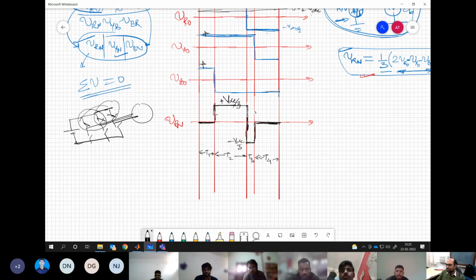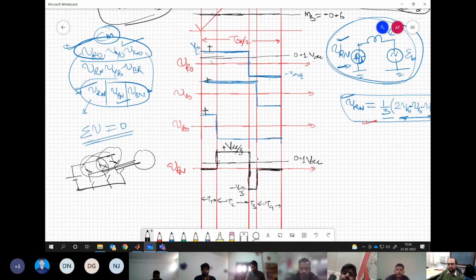They're the same thing, but in a different way. Same fundamental, yes, sir. In a different way means only the common mode is gone. Correct. But the average value will remain the same. It will remain 0.1 VDC. You have not changed the fundamental, you have changed only the common mode, you have removed that, that's all. The average of this is the same as what you got earlier.